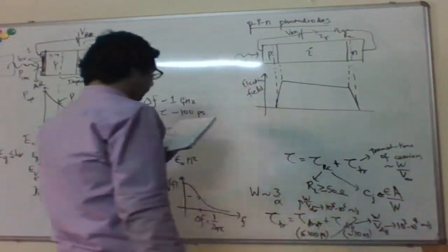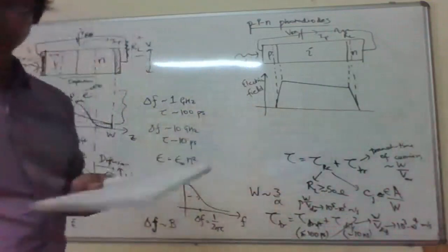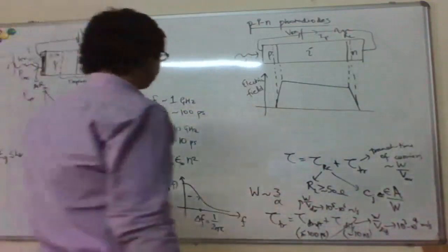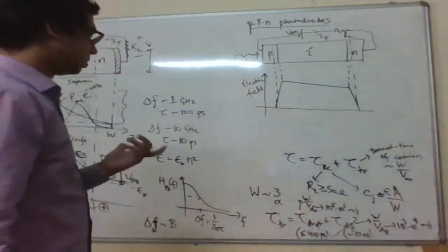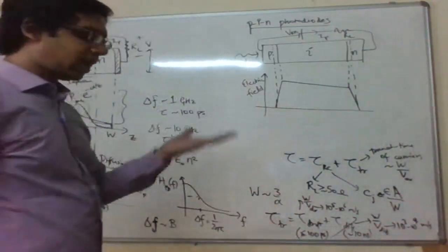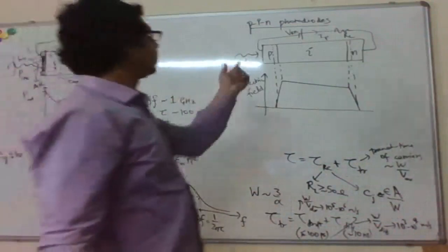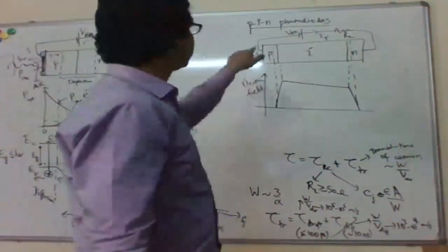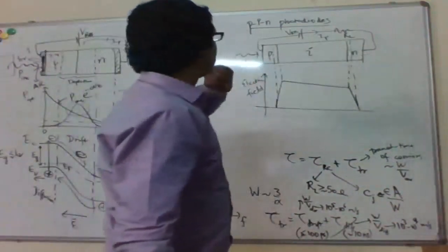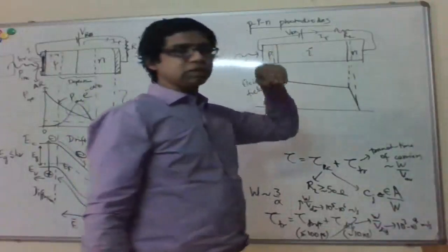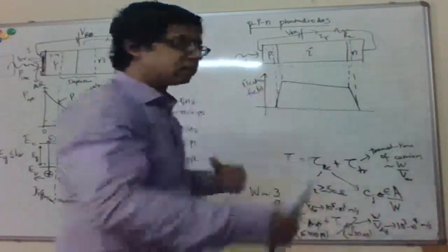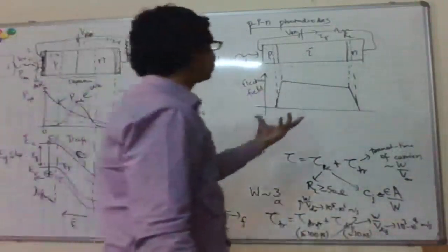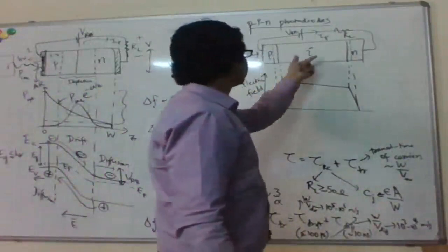Okay, and then you can do a further modification just like for the sources, right? Remember we had this double heterojunction kind of structure so that the light emission only happened in this. So we had an active layer there, right, between the P and N regions. And the active layer band gap was smaller than the P and N region, so that the carriers sort of collected in the active region and recombined only there. So we can do something similar here.